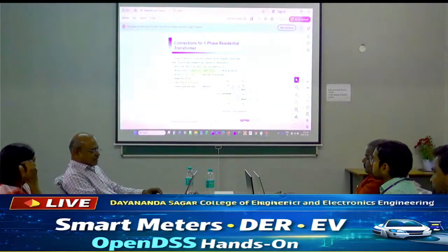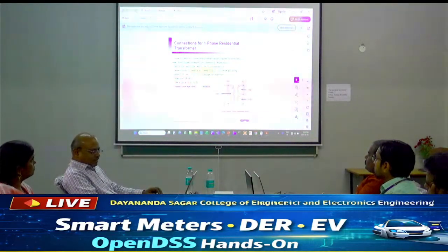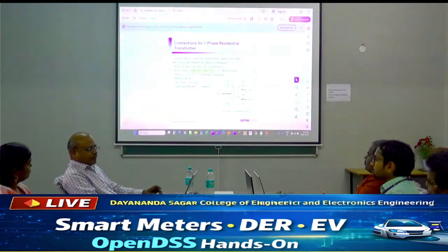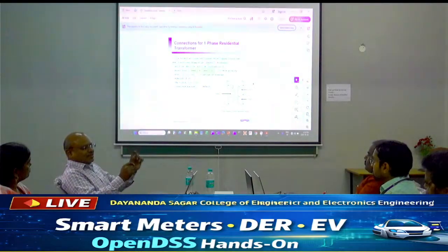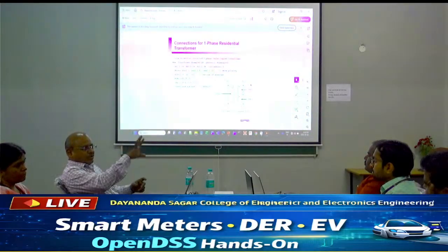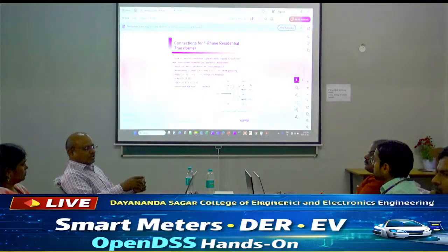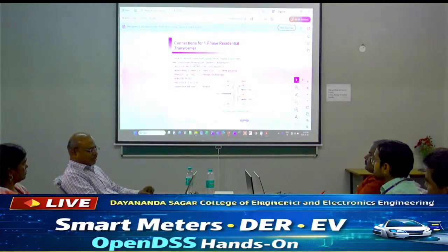Now in this case, this is defining a transformer like this. This is actually a typical US transformer. You have this double winding transformer where on the low voltage side it gives 240 volts with the center tap, so that you have 120, 120, which will be 180 degrees apart. So you can use 120 volt devices also, and 240 volt devices also. It is called a three wire single phase. Only in the US they use that. It is basically two 120 volt circuits with 180 degrees phase shift.